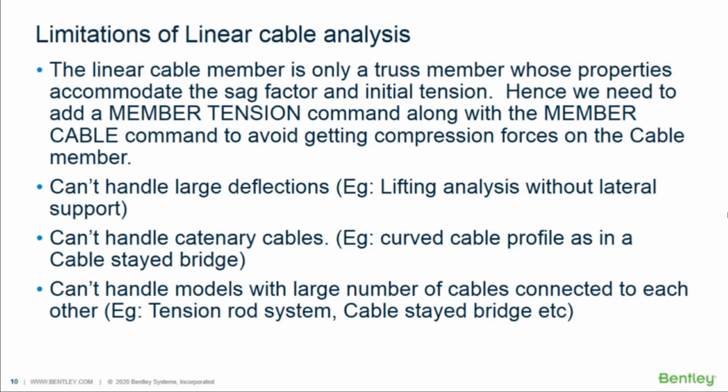And another important limitation of this linear cable analysis is that it can't handle catenary cables, the curved cable profile as in the cable stayed bridge. Also, this linear cable analysis can't handle models with a large number of cables connected to each other. For example, tension rod systems, cable stayed bridges, etc.